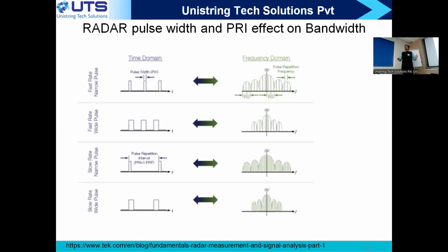If your sampling rate increases, your computations need to be faster. If it is a processor-based computation, before the next packet arrives, you have to process this packet and be ready. If it is an FPGA implementation, you would require your FPGA blocks to be clocked at a higher rate, which imposes implementation constraints. And there are other challenges of noise.